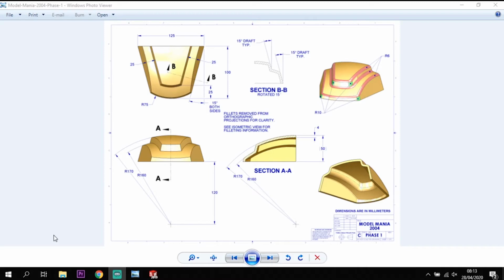Right, so with this, what we're going to do is break it down into sections. First thing I need to create are these curvatures around here. Now I've got some radiuses for these, so we'll look at creating some sort of shape to extrude these up to, probably using a surface.